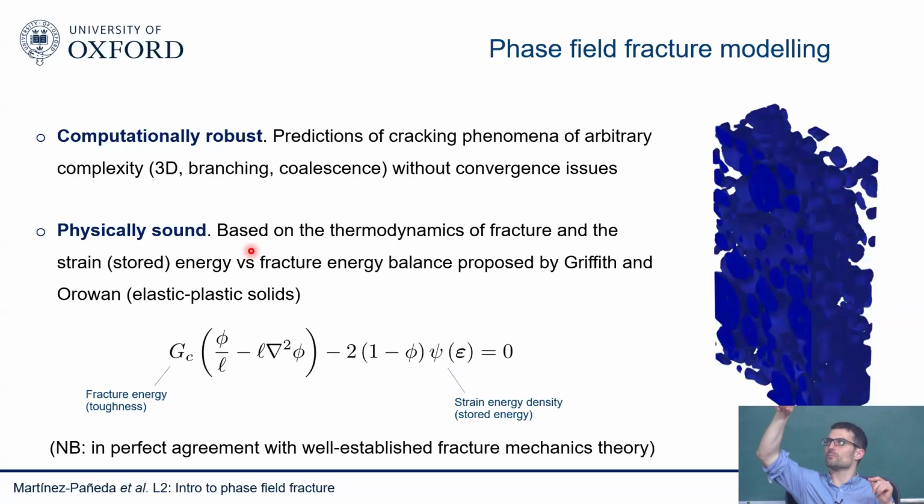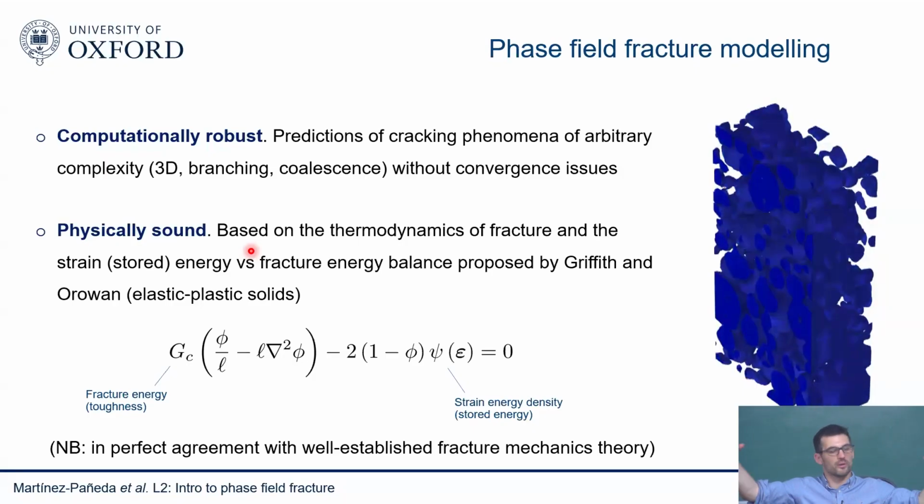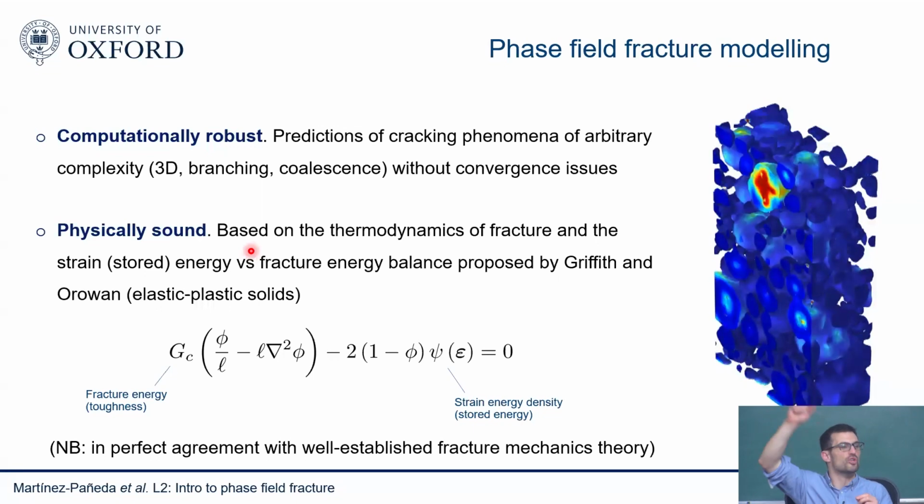And then suddenly you go from a peak load to unstable crack growth. Your crack has dropped, and the Newton method has to jump from here to a result that is very far away. So damage mechanics is always a problem for convergence because it's difficult to go from a sample undergoing loading to something that cannot carry any more load. It's a big change in the solution. Just to make it simple, it's very difficult to handle. This method seems to be able to handle it. I will discuss that a bit later on.